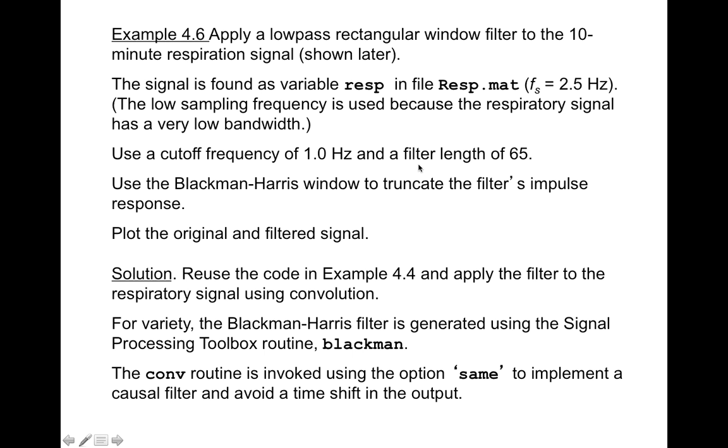Another example, let's apply a low-pass rectangular window filter to a respiration signal. Going to use the Blackman-Harris window in this case, and we want to apply this filter using convolution. So I just want to say here that MATLAB has many toolboxes that avoid having to use convolution.